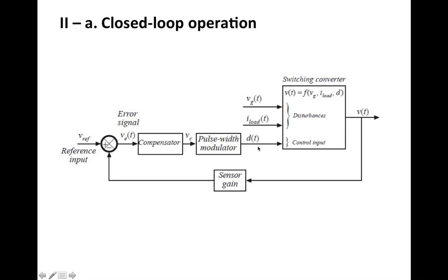So even if we adjust the duty cycle to be that exact value for the beginning of the operation of the converter, over time all of this variation is going to change and we won't have the accuracy on the output side. So the solution to this problem is a feedback system where we sense the output voltage with a sensor, and this can be simply a resistor divider.